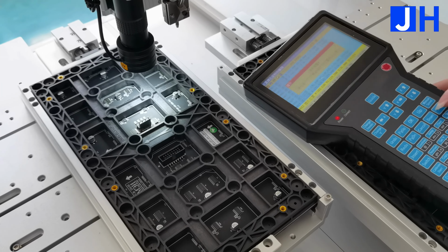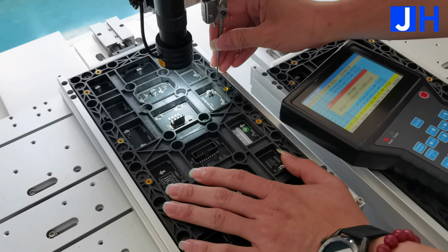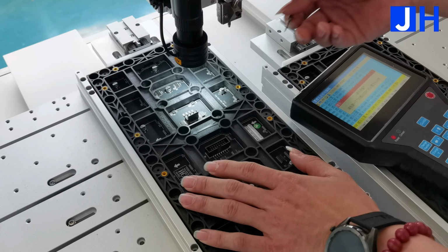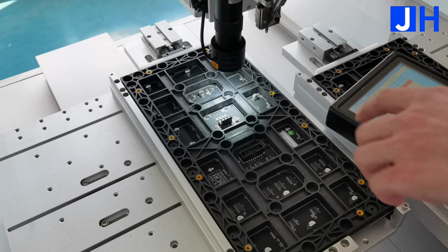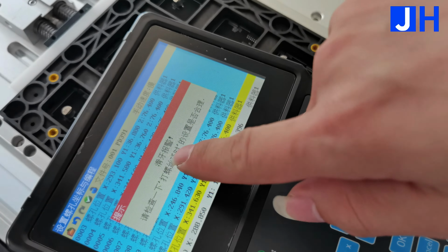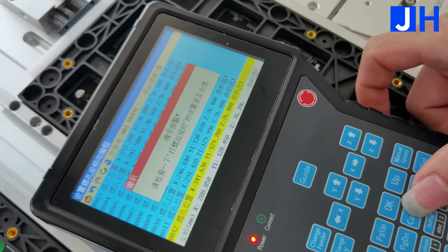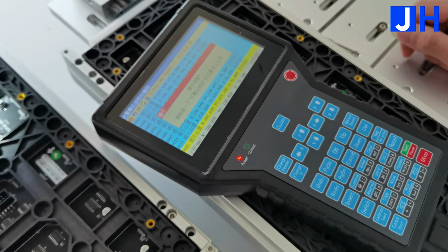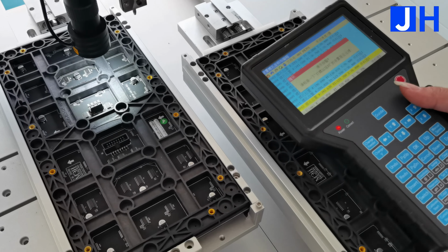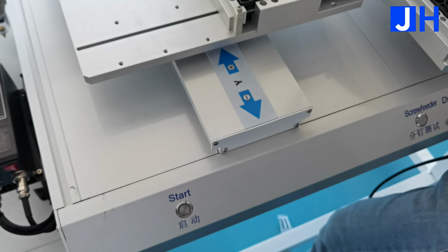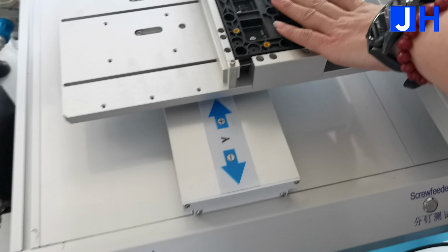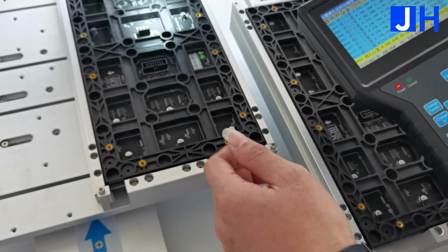This alarm was triggered because the torque was too high and the teeth were slipping. The PCB threads are damaged. PCB screw holes cannot be assembled or disassembled multiple times, as this may easily damage the threads. If the machine alarms, but you want to continue to operate it, just click the Start button. You can press Cancel or go back to the original point.